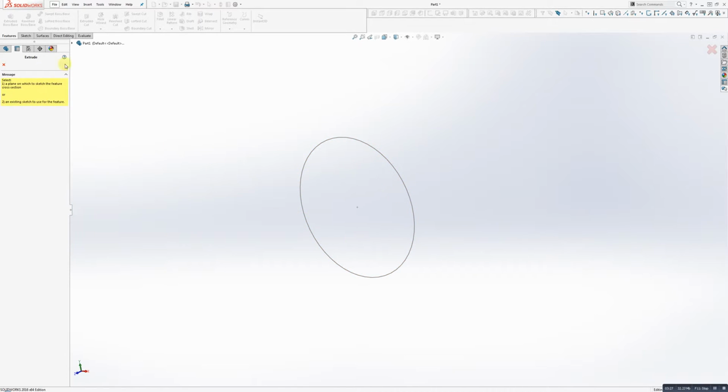But you can also unfold your design tree in the design area here, and then you'd have access to the sketch in the tree, which seems odd right now when we only have one sketch in our lineup, but once you get into a much more complex model, you're going to have sometimes over 100 different layers to your design tree, and finding an individual sketch is a little bit easier when you're able to go through the list as opposed to digging through your model, hiding and showing different parts of it to reveal the sketches you're trying to edit.